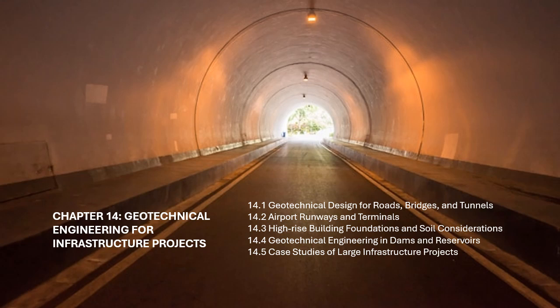Geotechnical challenges. The region surrounding the Panama Canal is characterized by highly varied soil conditions, including clay, silt, and volcanic rock. The canal's proximity to active fault lines and the need for a stable foundation under the new locks created additional complexities. Engineering solutions. Extensive geotechnical investigations, including soil sampling, borehole testing, and seismic hazard assessments, were carried out to evaluate the soil and rock properties.